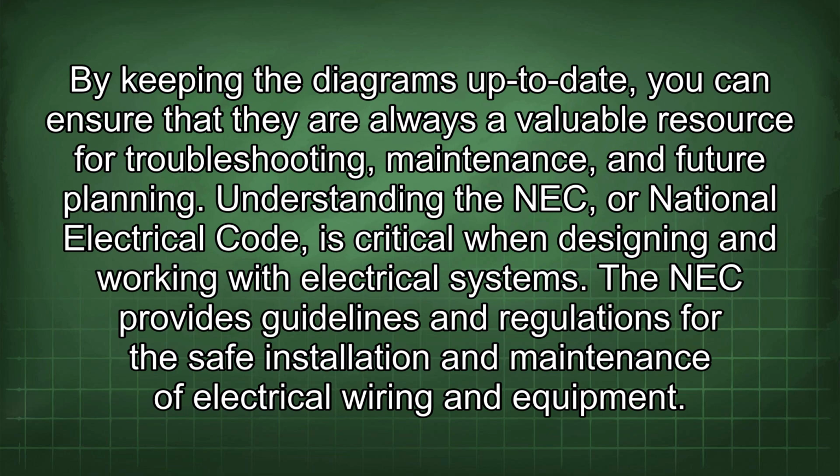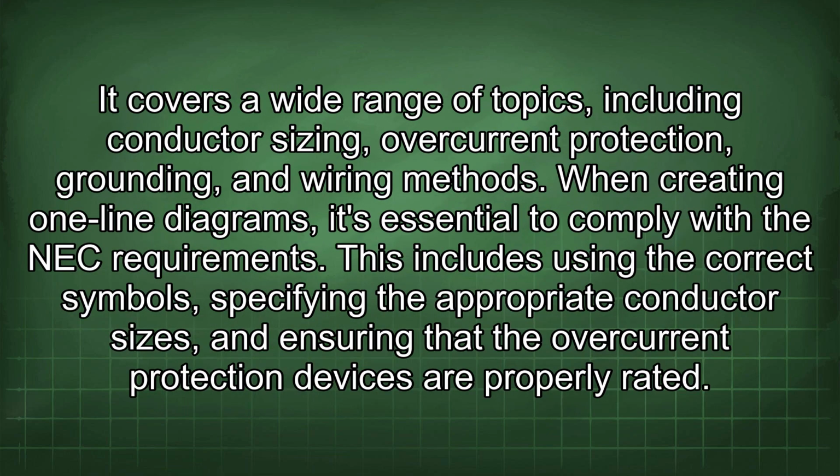Understanding the NEC, or National Electrical Code, is critical when designing and working with electrical systems. The NEC provides guidelines and regulations for the safe installation and maintenance of electrical wiring and equipment. It covers a wide range of topics, including conductor sizing, overcurrent protection, grounding, and wiring methods. When creating one-line diagrams, it's essential to comply with the NEC requirements.